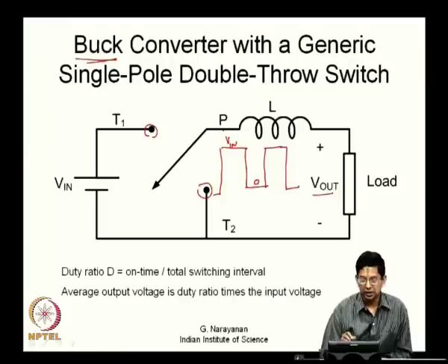So, what you get is such a pulsed square waveform. Now, this has a certain average value, and this is the average voltage that we require for the load. The average voltage dropped across the inductor is 0, so the entire average goes through the load. The inductive filter serves to smoothen the current as we saw before, and we can also have an additional capacitance connected across the load for further smoothening of the current, and to smoothen out the load voltage too. The output voltage here is basically the duty ratio times the input voltage, as we saw.